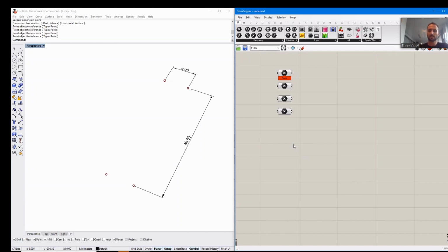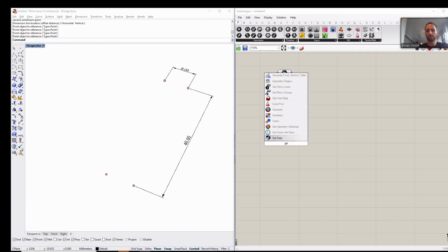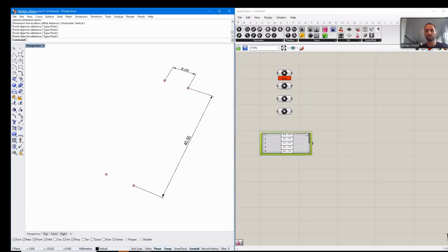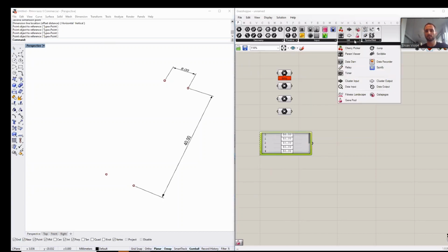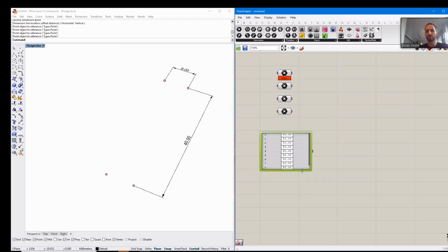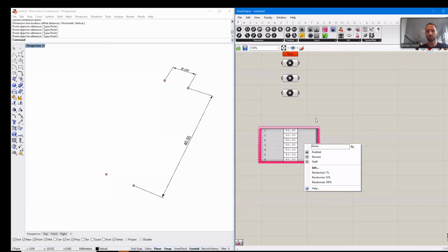So sorry, what I've done now is I'm creating a gene pool. This also comes with Grasshopper. It's in the parameters utils tab. So we have here the Galapagos component that comes with Grasshopper, and made for this kind of application, more or less, the gene pool component, which is basically nothing more than a set of number sliders in one component.